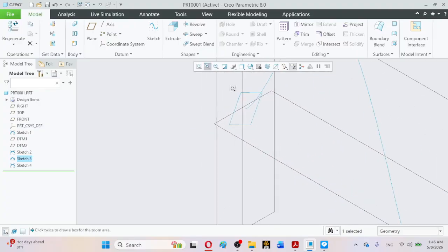Here one important thing is also that the section somewhat looks similar, or you can say parallel. The section plane looks parallel to the tangent to the start point of this trajectory.